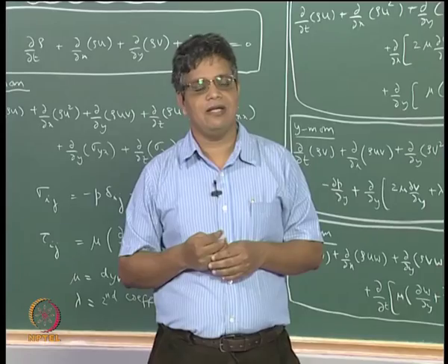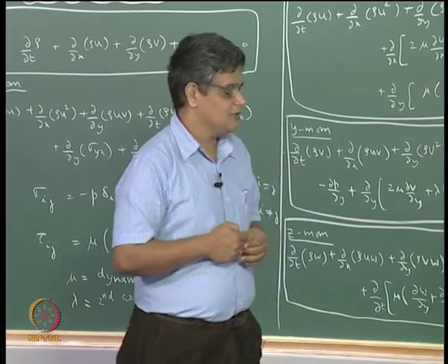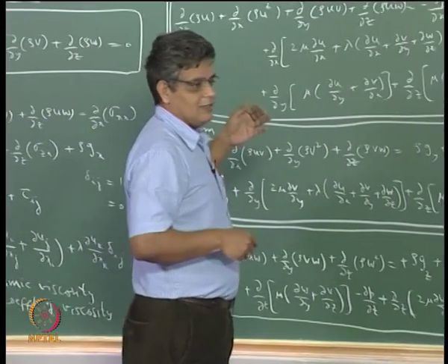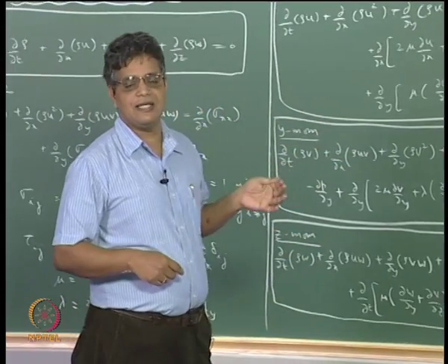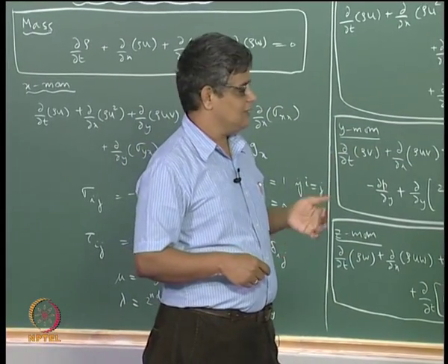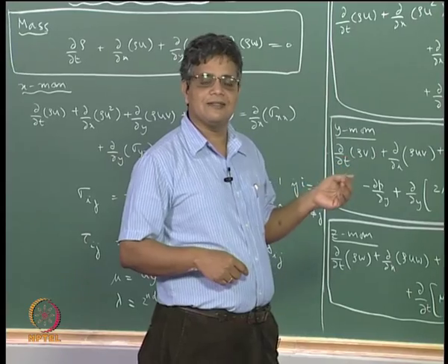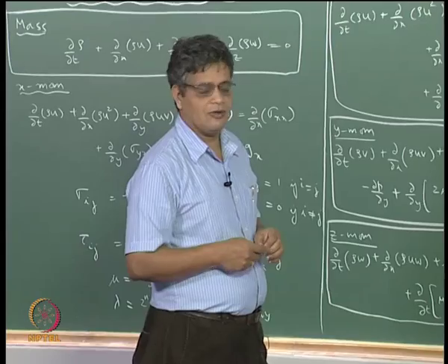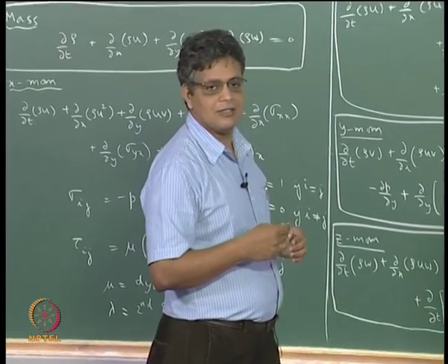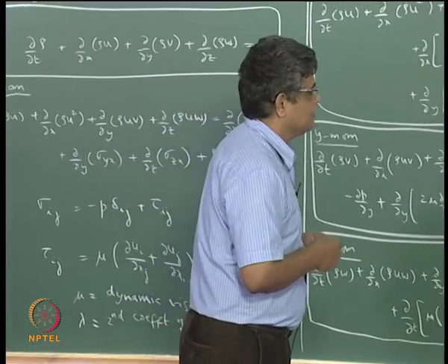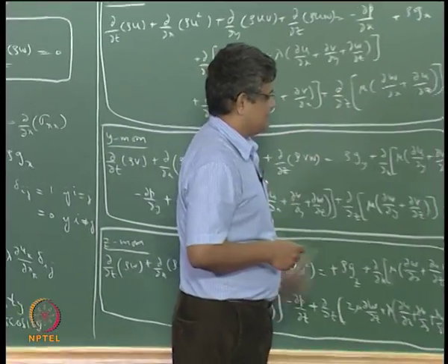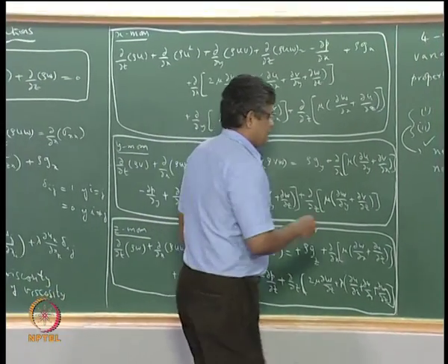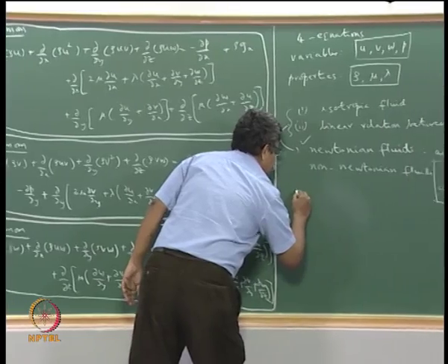for us to consider seriously the effects of compressibility. So from that point of view, we can say that when the velocity of the flow is not very high compared to the speed of sound, typically if it is less than a third of the speed of sound, or if the velocity is less than 0.33 of a Mach number, then we can say that the fluid is incompressible or the flow is incompressible.